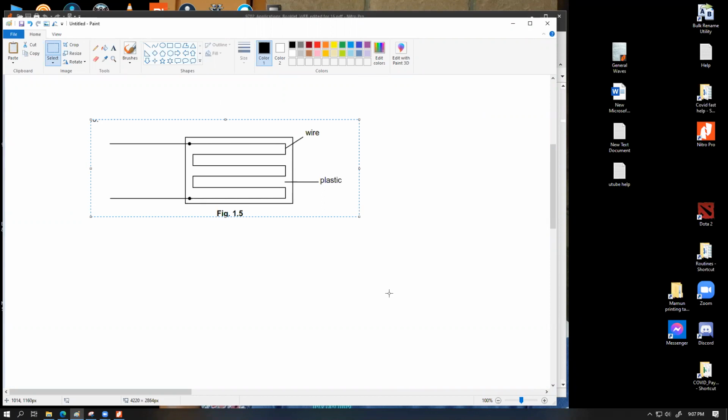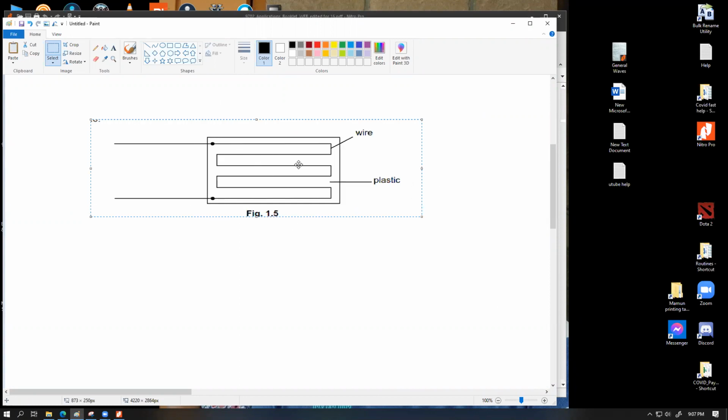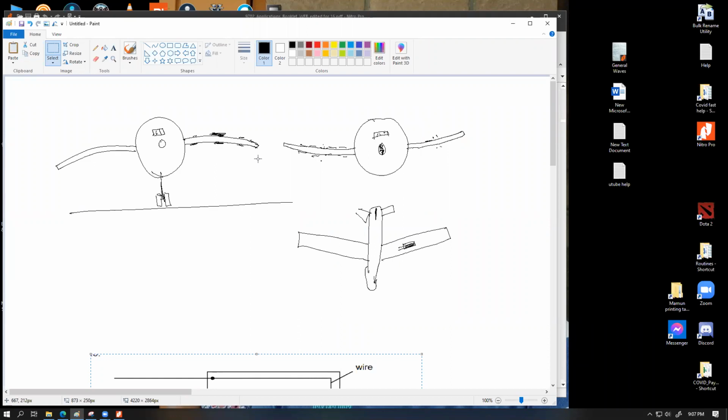So if the strain gauge undergoes extension, the whole strain gauge will extend, and you're going to have a lengthening of these wires. These vertical parts are not lengthening very much, but these long parts will undergo a large amount of length increase. If you wonder why you need so many wires, why not only one wire? The idea is the amount of increase for one wire length is actually very small. We're talking about bending of the wings, and these things are not like 1 foot or 2 feet long. These are pretty small devices.